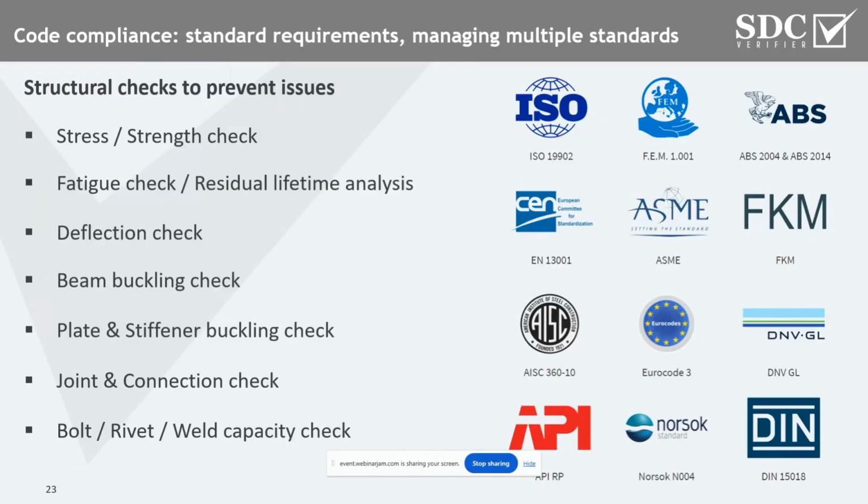And that is really posing a big challenge, because on the one hand side, you have many checks, many complex procedures. On the other side, you have also some standards you would like to combine. For example, I don't know, the same offshore industry. Yeah, so you want to use API in combination. Yeah, API, let's say for tubular checks, but AISC for other members, or joint check, let's say according to API or the same ISO or NORSOK, and then the other ones for different things. So this is really tricky part over here.